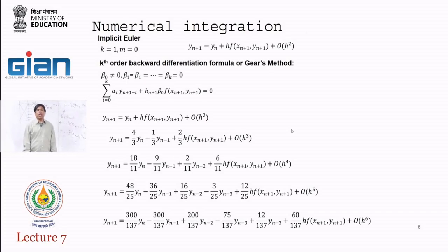And it is okay to actually go for a higher error. Remember, generally as researchers, we always want the highest accuracy. But one thing you have to always keep in mind is the stiffness of systems. So when a variable changes like this, it goes like this. This is extremely steep. It's almost like a vertical line. Most solvers have trouble getting into that.